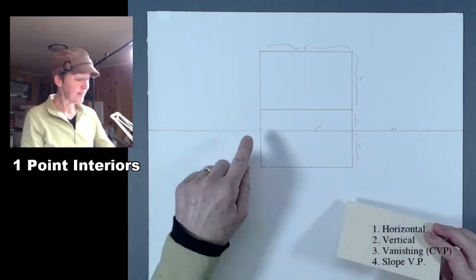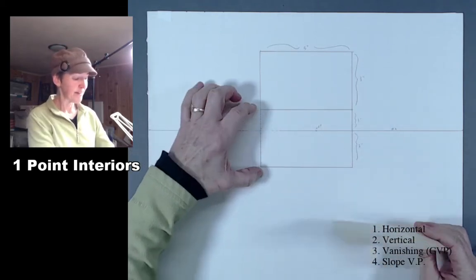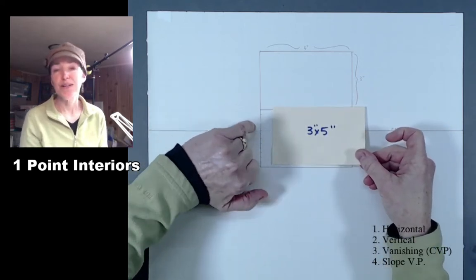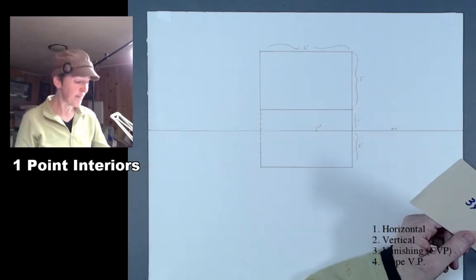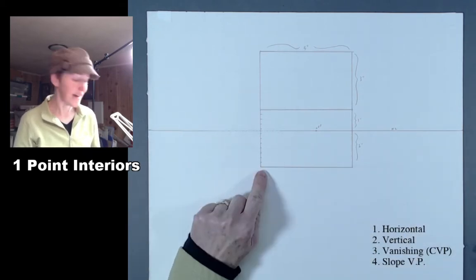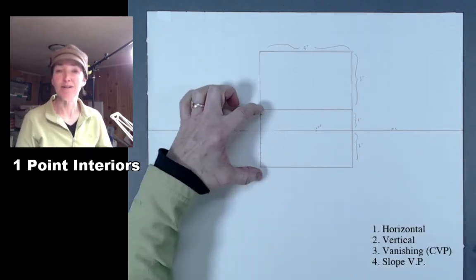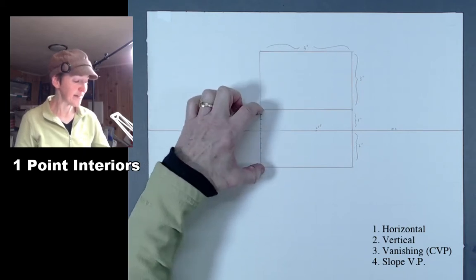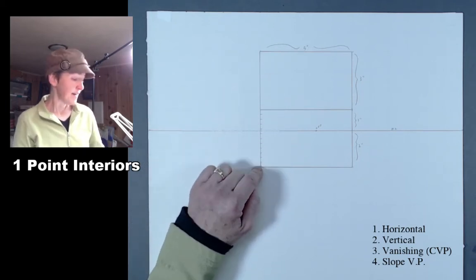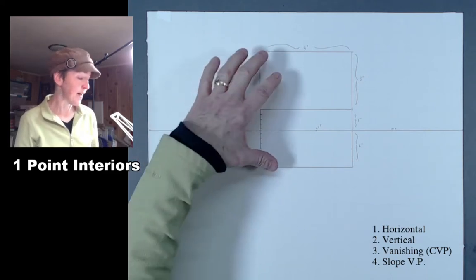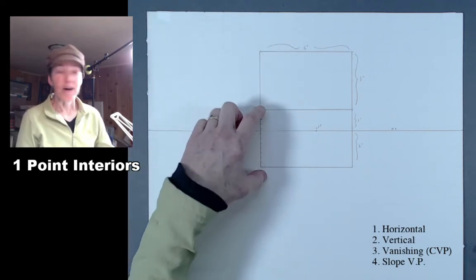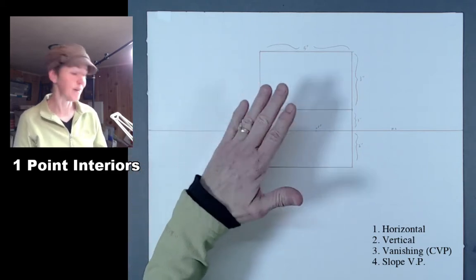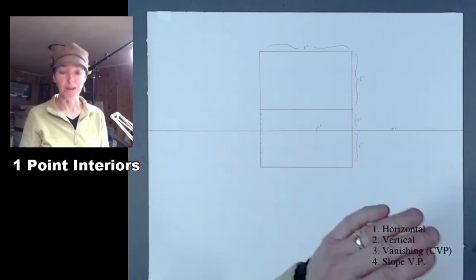The other thing I'm going to need you to do is on this 3-inch section, the lower one, I want you to rule off 1/4 inch increments. So I'd like 12 divisions in that edge of the block there. So again, if you do a 3-inch rectangle, it's really easy to fit 12 in there. And once I get this expanded out, I'll show you how you can also slide your ruler along to find those even divisions anywhere along that foreshortened wall.